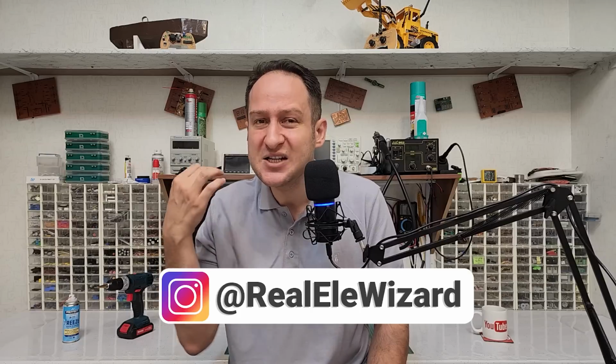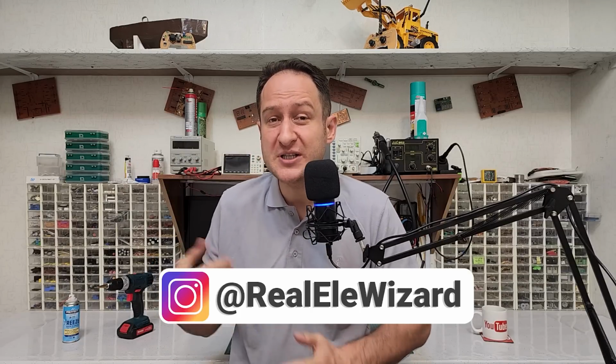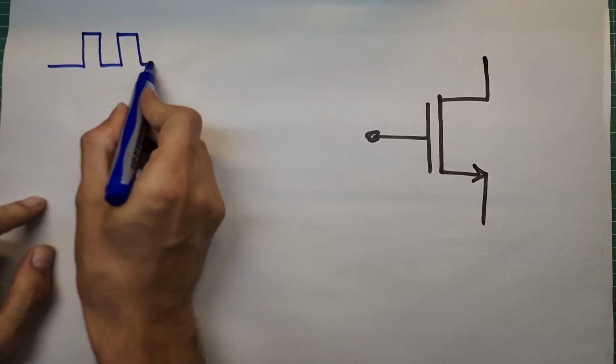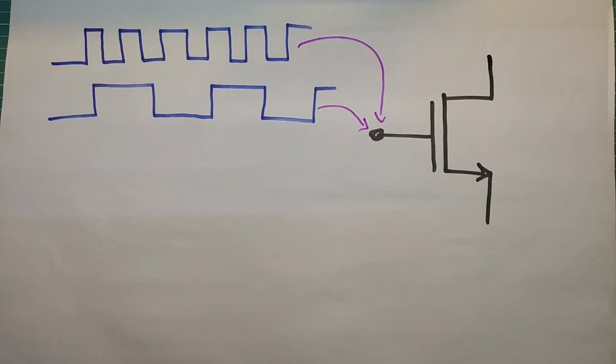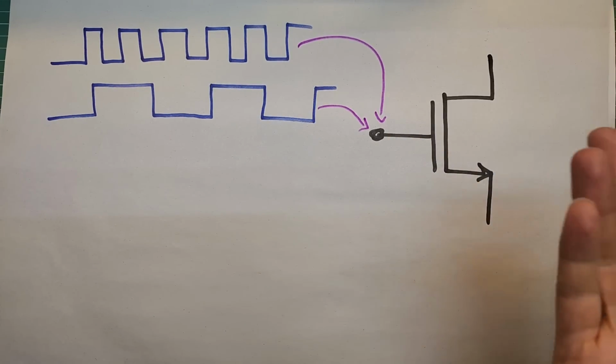A BJT has a simple biasing circuit, but a FET needs more complex biasing circuitry because a FET transistor has to switch quickly. I mean, you have to do your best to charge or discharge the input intrinsic capacitors of a MOSFET as quickly as possible, even when the switching frequency is low. I think it needs to be clarified. Regardless of the frequency of the gate pulse, we have to switch the MOSFET quickly.